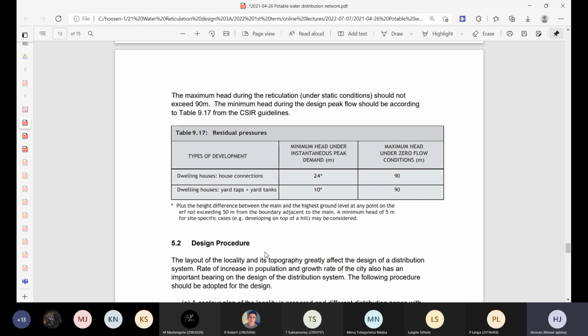So you will then have air in your system, and as the water flows, the air increases at one point in the pipeline, and the pressure increases at another point, those air bubbles will then collapse. That collapse is usually dramatic, and it can damage the walls of the system. It's sort of like an explosion that takes place as those air bubbles collapse and go back into solution. So issues like that arise.